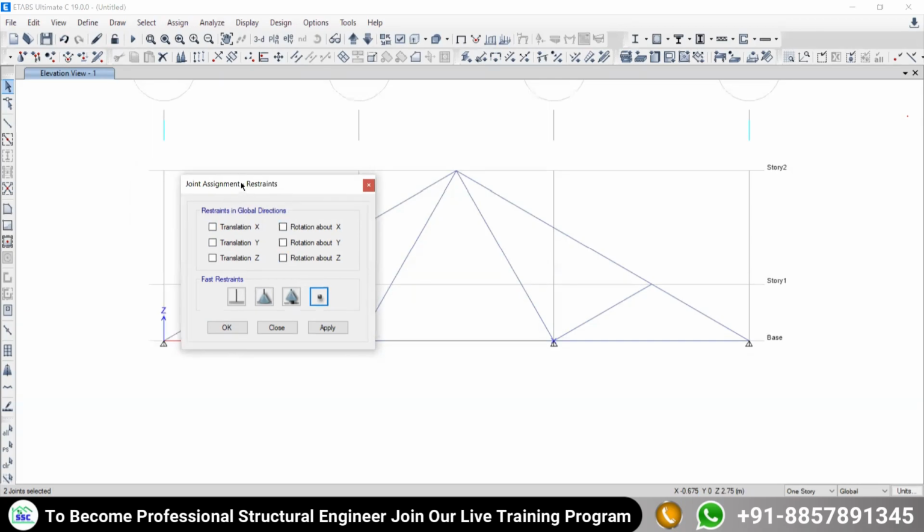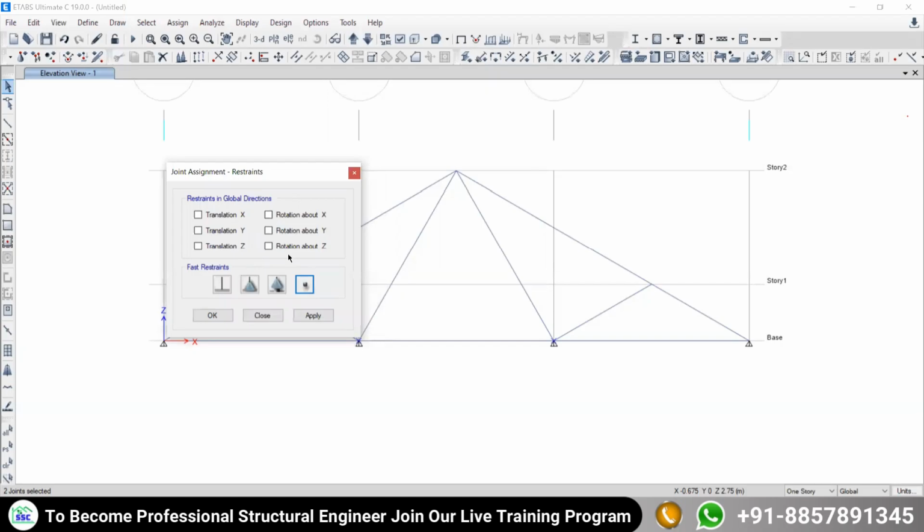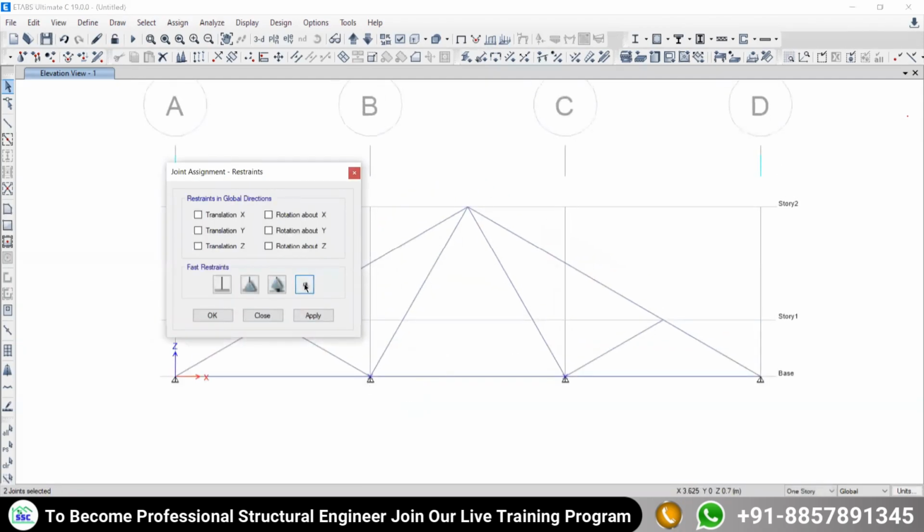I'm not going deep into explaining these things. It's very basic. If you are not well aware of it, just search it and understand it. But if you are not willing to look at that, directly focus on these images, these icons. If it is fixed, the restraint will be selected accordingly. If hinge, hinge restraint will be selected. If roller, roller restraint will be considered, and then none. Now, is there any support here? No. So select this None, apply. So none is there, nothing is there.